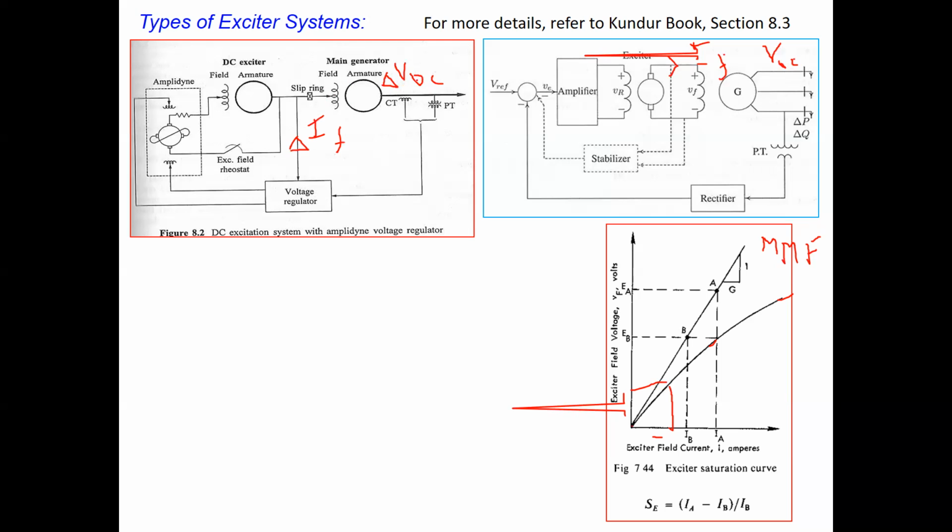And again, this is open circuit. That means the generator is not loaded. But when you load the machine, then again this voltage will change. All right. Because there will be a current flow in the stator here, so this voltage will change. So it is important how the terminal voltage at the loading condition changes with the field current. So that is again another part, how we are able to achieve a relationship between this terminal voltage and the field current here in the exciter modeling, right?